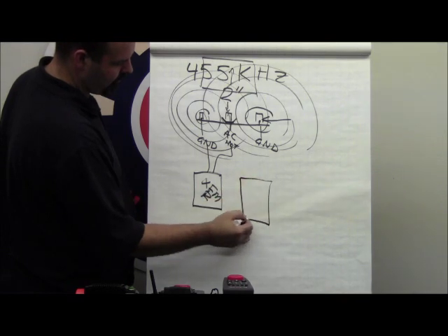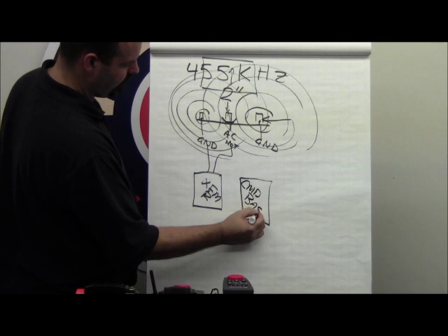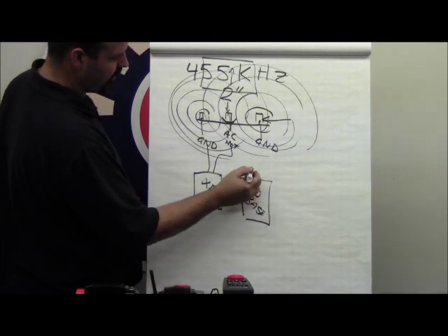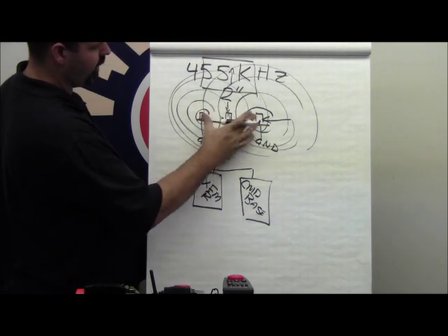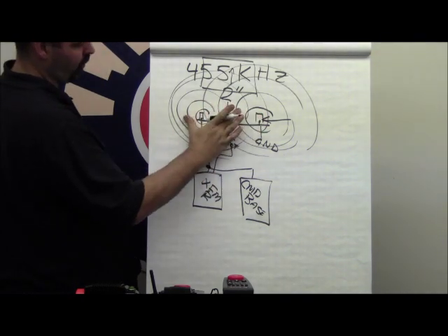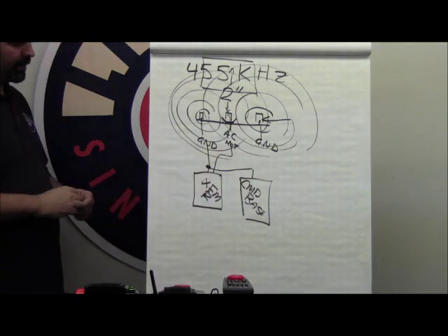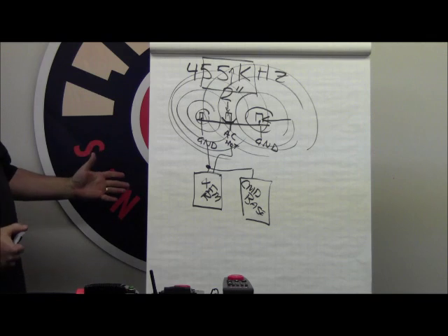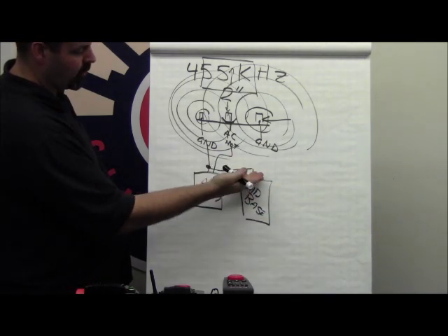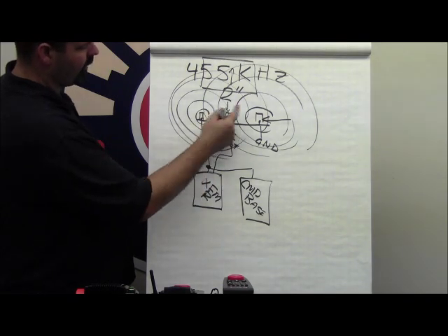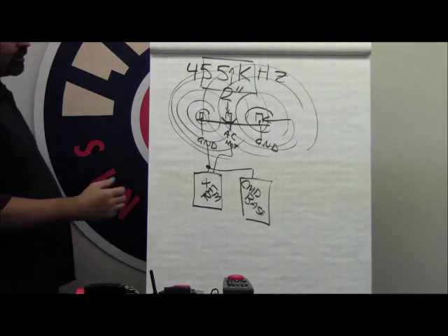Our command base is putting the signal on the AC ground or outside rails of both rails. This wire has absolutely no polarity. It's not hot and it's not ground when it's disconnected. It becomes ground because it's tied to the outside rails, which are AC ground for the track power.